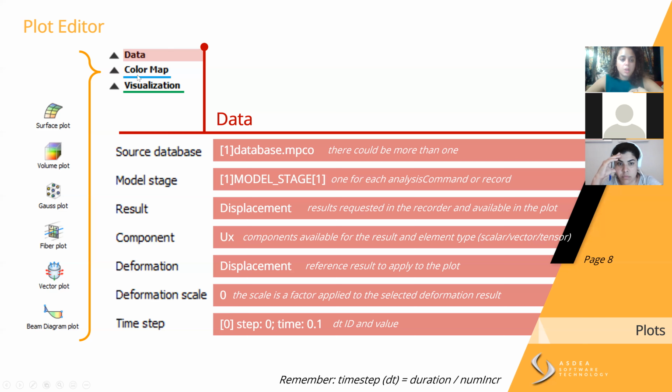So these things I'm talking about are not true for this kind of plot that I actually erased. Then there are some additions. If you have results at the end nodes of the elements, which we will talk about at the end, but we actually discussed them in week 3 too, like local forces, which are results at the end of the element in the conjoining node that can be different at the two extremities, you can operate a smoothing by clicking on the nodal average option that will appear if you select this kind of results.